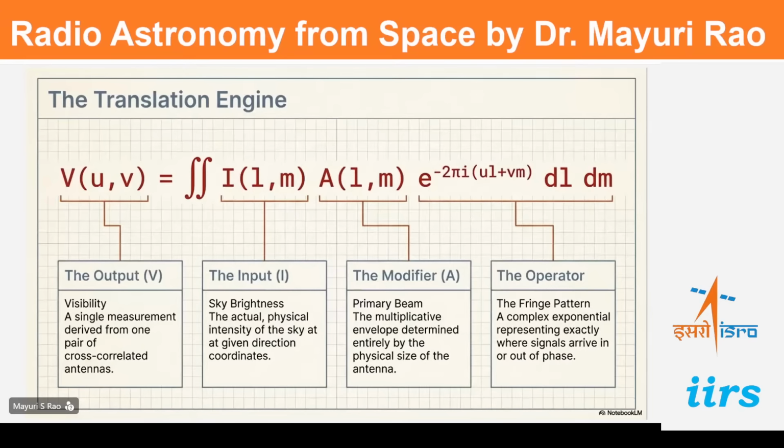Then each of your individual antennas has some beam that senses this radiation. The next part, the exponent term, is the trick that converts this into meaningful information for us, where what you're doing is actually a Fourier transform operation. So you're taking the sensing aspect of the individual antennas and the source radiation and taking a Fourier transform of this.